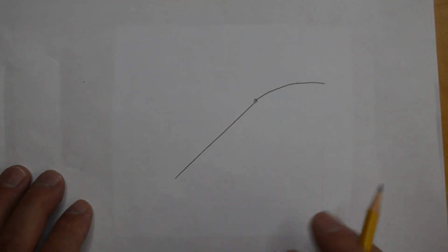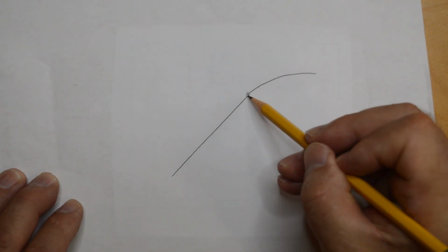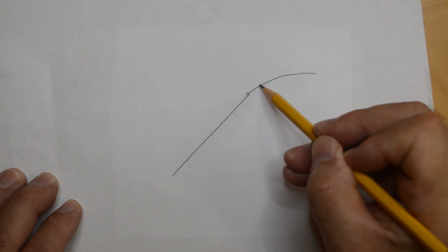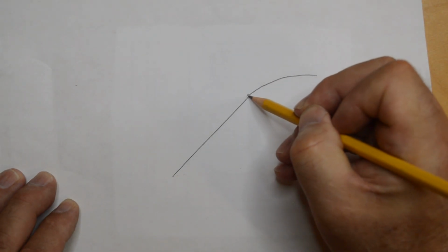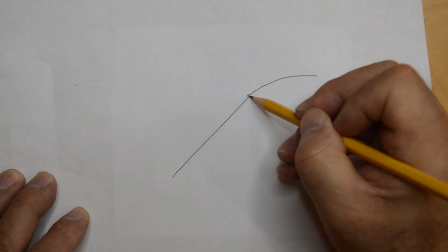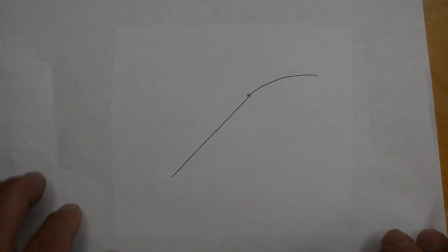So it could be useful to us to get at those points, especially given what they mean. For instance, you have some line, and then it is exactly tangent to an arc, and the arc takes off. Well, that point might be interesting to us for further construction. Okay, so we allow you to get at that point and extract it from the database and establish it as a point in the user geometry database.